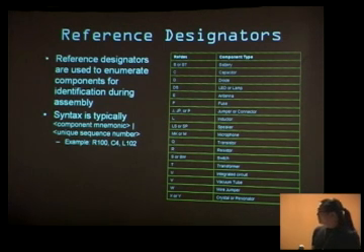There's a long list of stuff. I'm not going to go through all of them, but basically you take the first letter, typically, of the component and make that the first part of the reference designator, and then you add a unique sequence number to it. That's the syntax of a reference designator. I don't know why transistors are called Q. Maybe because T is taken for transformer. Integrated circuits are U, I think, for the micro symbol back in the day.